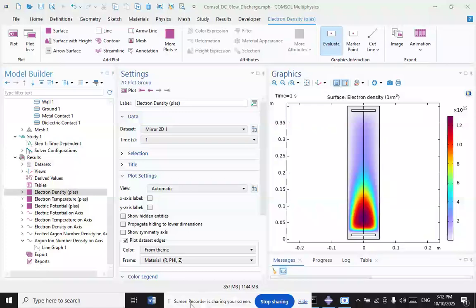Radio frequency discharges are generally operated at a frequency of 13.56 MHz allowed by the International Communication Authority. Plasma characteristics such as density and composition influence the characteristics of the film deposit. Non-thermal radiofrequency discharge is subdivided into two types, namely low pressure discharge and moderate pressure discharge.